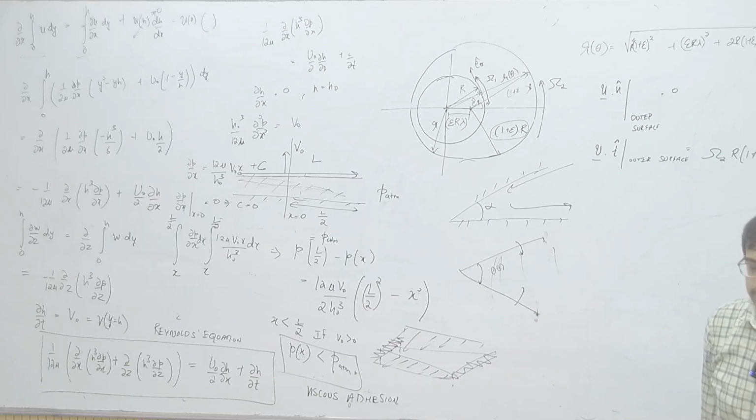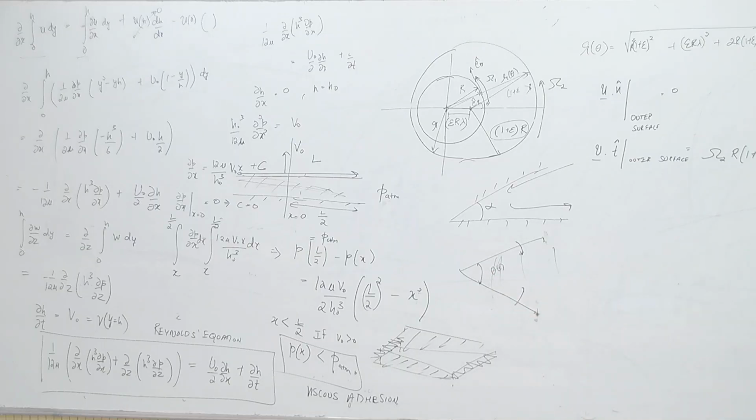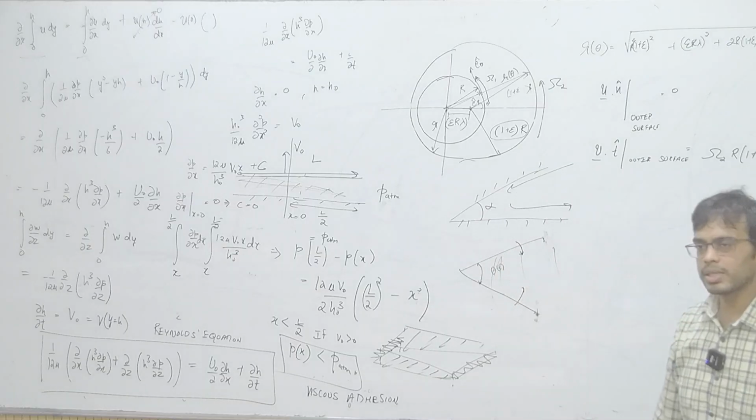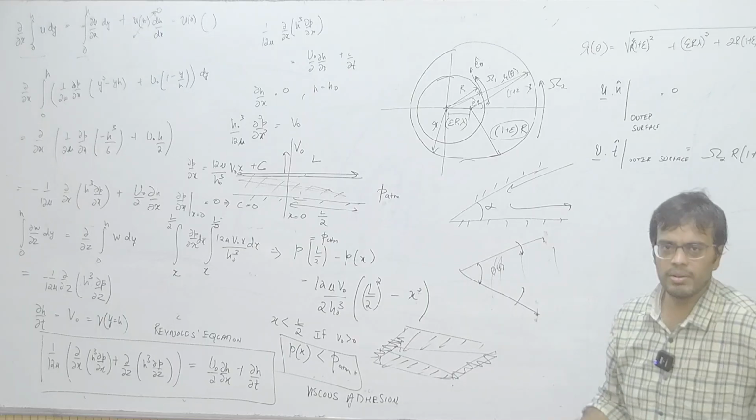and in the limit of low Reynolds number you can solve for that kind of a flow as well. Then we moved to lubrication theory, where you may have two different length scales to define a Reynolds number, and we saw what are the limits under which lubrication examples can be solved. Low Reynolds number flow is a field of itself. Okay.